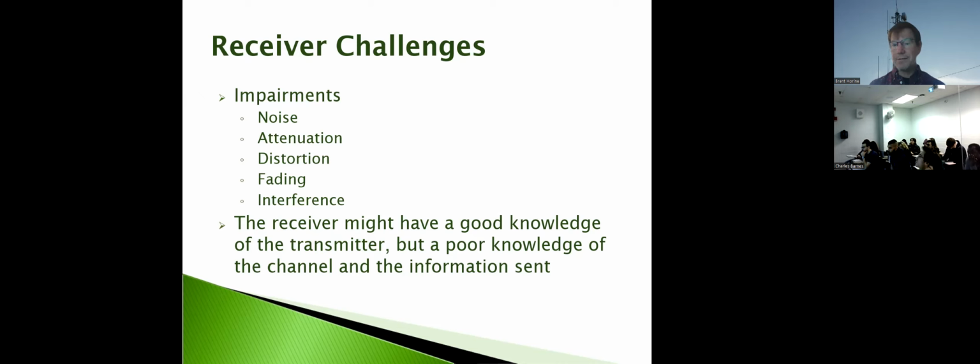But of course, there's every combination possible of those phases from 0 to 2 pi, right? And in a mobile communications situation, that is constantly changing. So you will have what we call fading or dropouts due to this multi-path interference, multiple paths in that transmission link. And of course, we also have interference from other users of the spectrum.